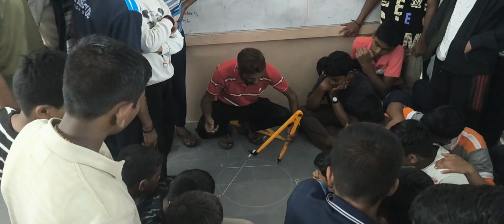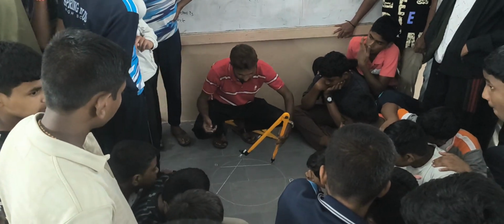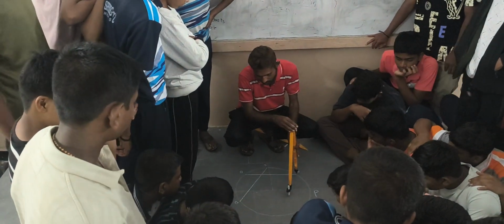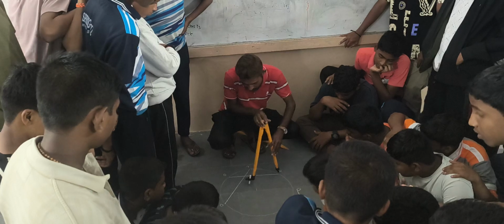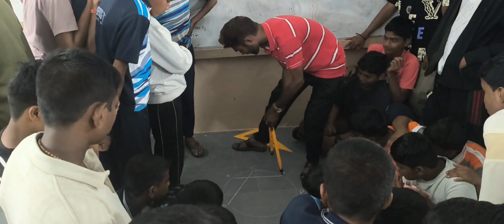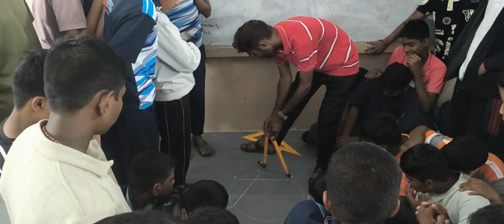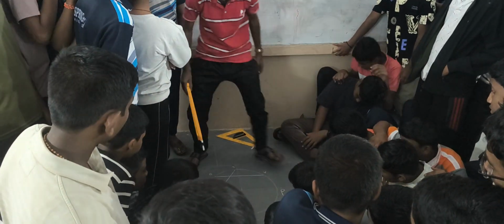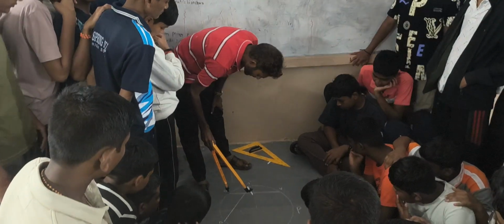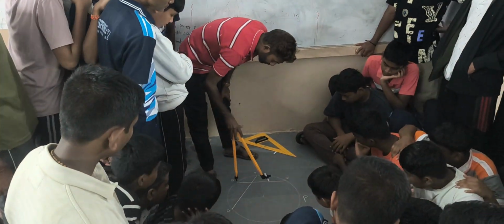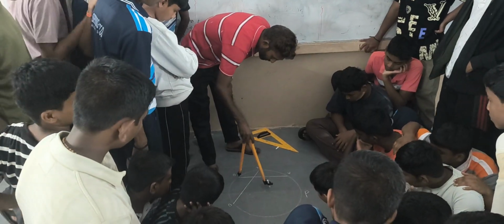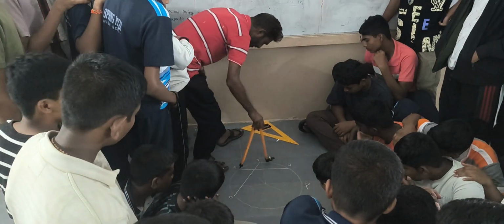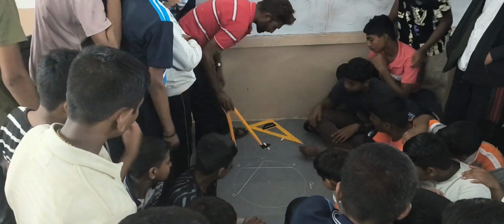Perpendicular bisector. So what is the condition to draw a perpendicular bisector? We need to draw more than half the length as radius. Draw an arc above and below, just like this. With center A. Now come back to this side. With center B. Keep the pointer of the compass at B and draw an arc above as well as below. There is one more.